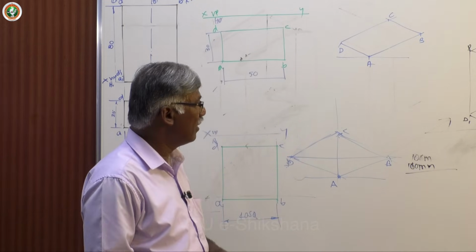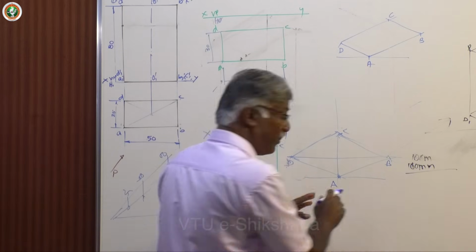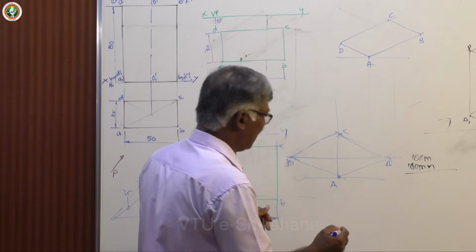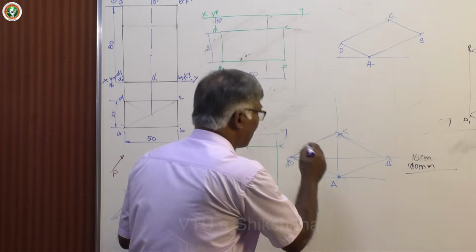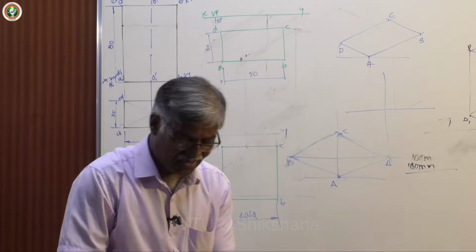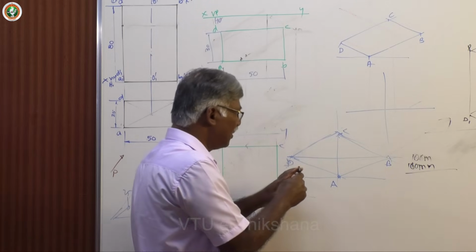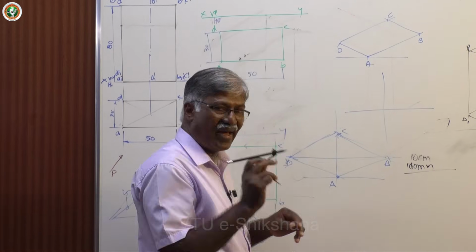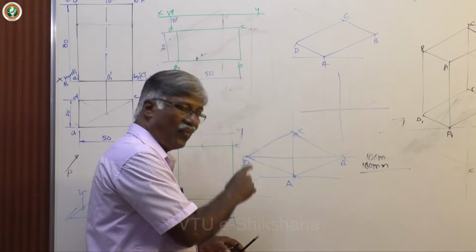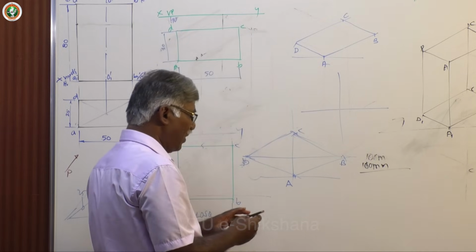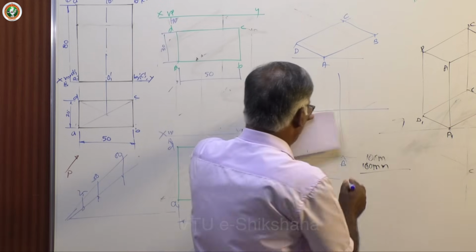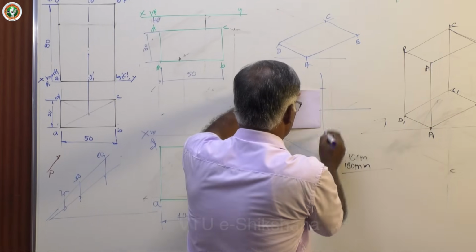What you do is draw a plus mark. I am repeating, be careful, take this procedure, it works well for anybody for that matter. Draw a plus mark. Plus mark is the best mark in graphics. Take the compass. Assume that I am taking the compass. The side is equal to 40. You take 20 mm, half of the distance, as the radius, and draw arcs. So assume that I am taking a 20 mm radius and drawing arcs with the compass.